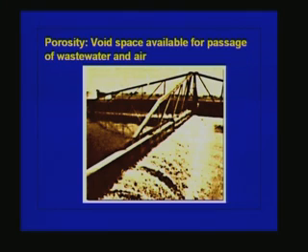So this picture shows a trickling filter. So this is the distribution system. So distribution system consists of a few distributing arms. So this is one, and here we can see many nozzles. So the wastewater will be coming out of the nozzle and it will be sprinkled uniformly over the trickling medium surface. So how is this distribution system working in a trickling filter?